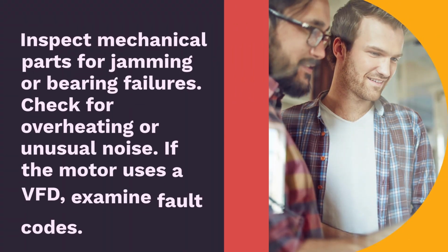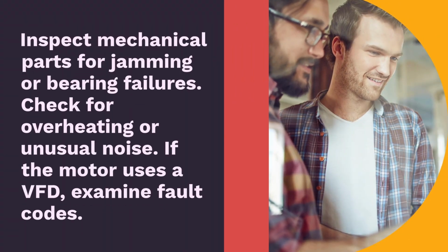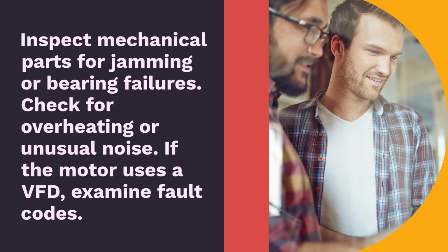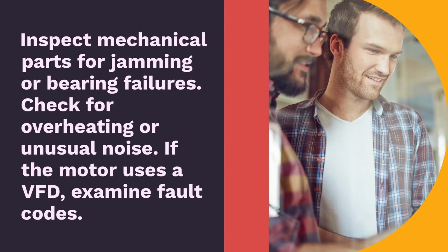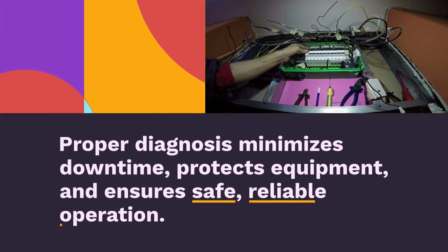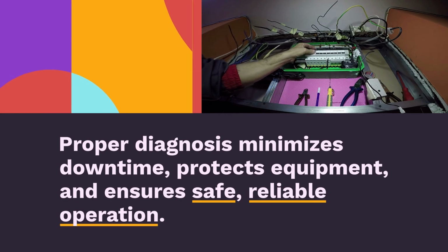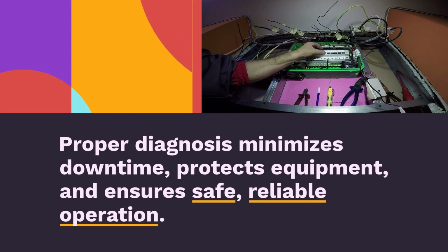Inspect mechanical parts for jamming or bearing failures. Check for overheating or unusual noise. If the motor uses a VFD, examine fault codes. Proper diagnosis minimizes downtime, protects equipment, and ensures safe, reliable operation.